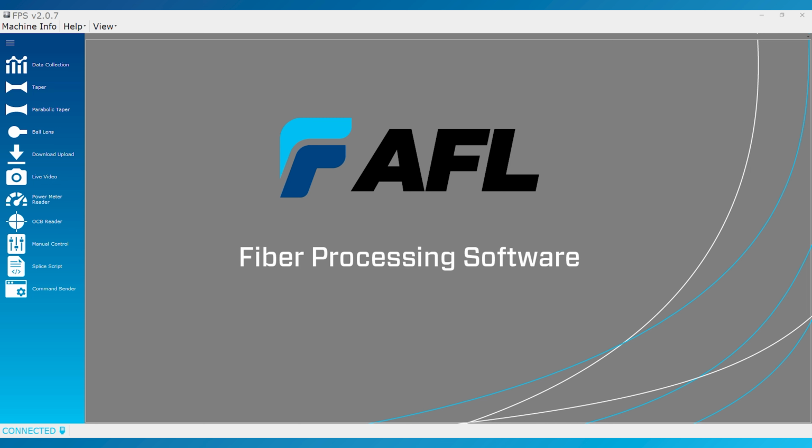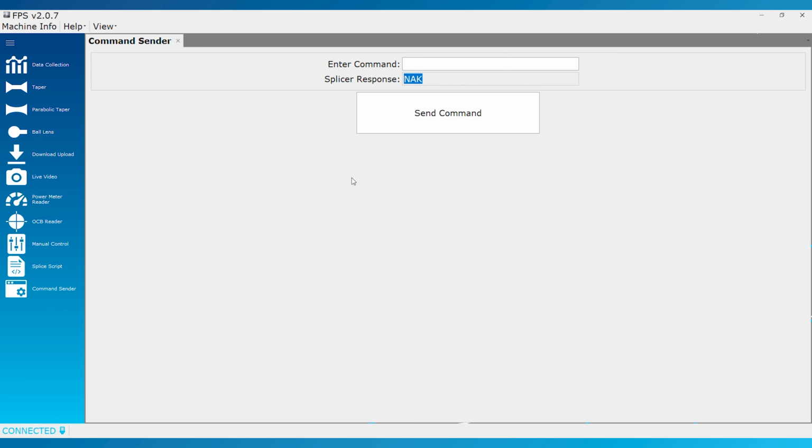The Command Sender module allows you to manually execute FPS API commands with the splicer. To test a command, enter the preamble character followed by the command string. For example, typing $reset and pressing Enter sends a reset command to the splicer. If the command is received successfully, FPS will return ACK, indicating command acknowledgement. If unsuccessful, it will return NAK, meaning the command could not be processed or was not acknowledged.